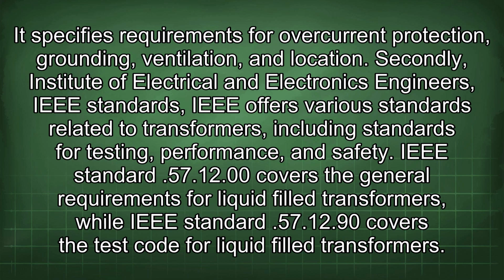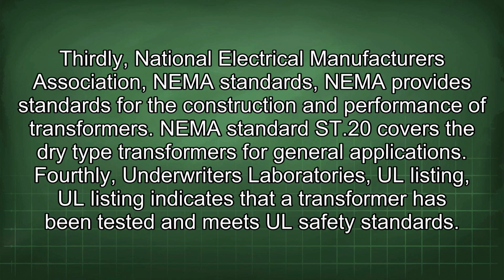Secondly, Institute of Electrical and Electronics Engineers, IEEE standards. IEEE offers various standards related to transformers, including standards for testing, performance, and safety. IEEE Standard C57.12.00 covers the general requirements for liquid-filled transformers, while IEEE Standard C57.12.90 covers the test code for liquid-filled transformers. Thirdly, National Electrical Manufacturers Association, NEMA standards.